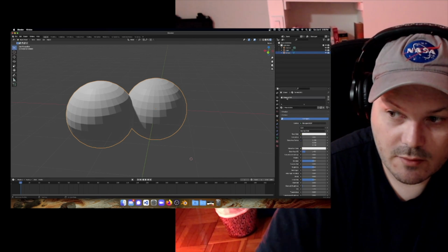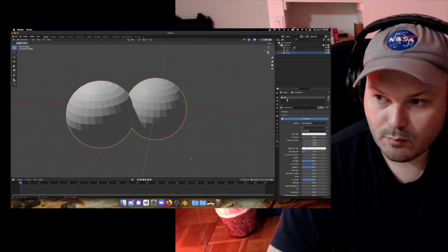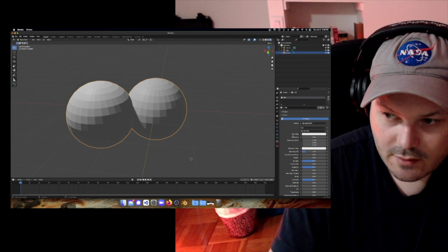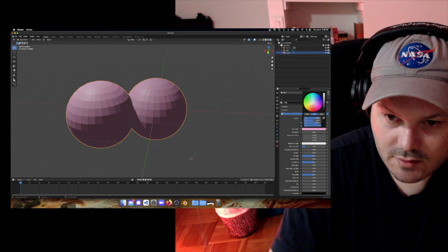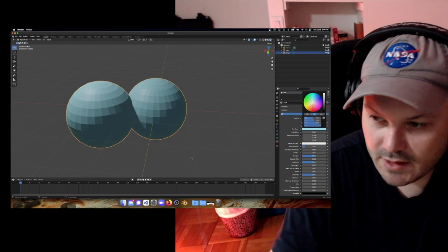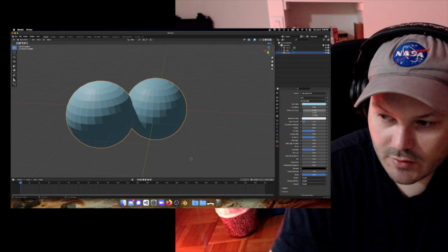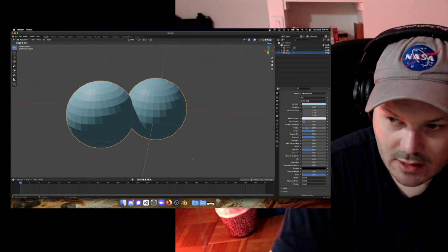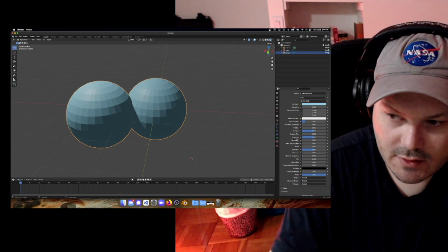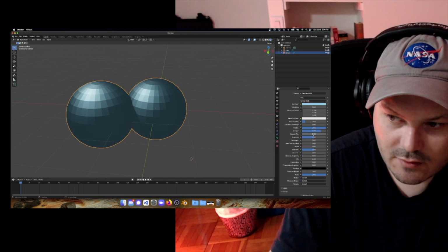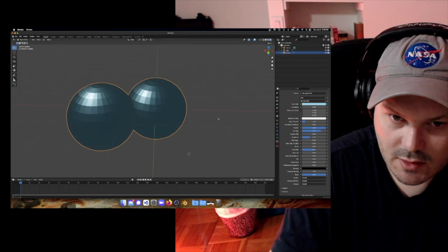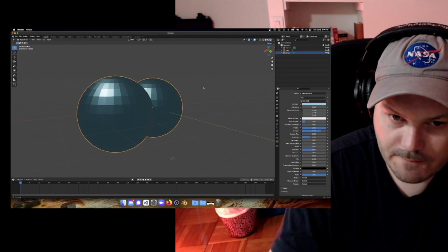And we're just going to mess around with a shader. So right now we've got our ball material added. And I'm just going to adjust the base color here. And this is just our, I guess, paint. And then you have additional properties like reflectivity, metallicness, specularity, roughness. So if I were to turn up metallic to 100% and specularity up, which is kind of how reflective it is, and roughness down, then we've got some shiny items.